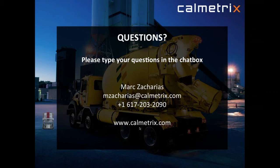But in terms of doing continuous mixing, no, you can't, because if you do continuous mixing and continuous measurements and want viscosity continuously, it won't work, because here you have your trade-off, your dilemma. If you use traditional impeller shapes, you can use the Bingham equation, but you don't mix well, so the concrete will segregate. So whatever values you get are junk, right? But if you have a Tritter impeller, there's no mathematical model, unless someone wants to start working on it. There is not, as of today, a mathematical model that correlates the two.